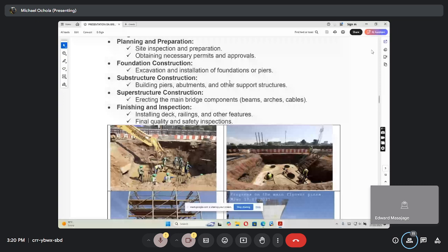So this is the Kampala flyover. This is the finished part. You can see, if you look at this support system there, you can quickly understand what went down here. And then the piles go down about 20 or 18 meters, 4 in number. They are 1.2 diameter piles. Now, there's something you need to know during construction: materials control and production of concrete.